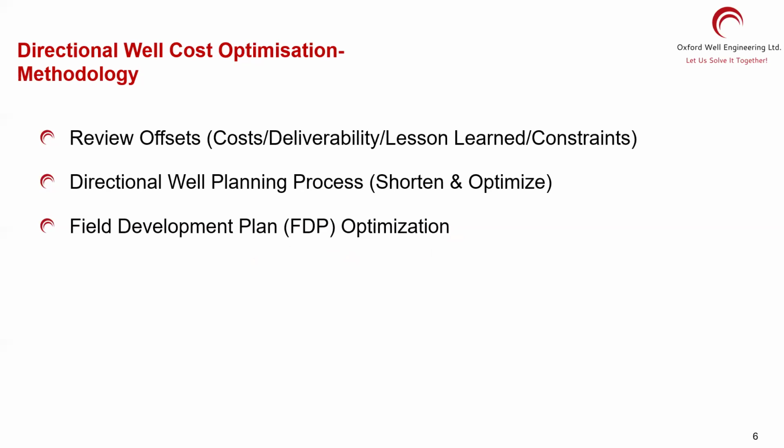Well design selection. Well design is a partner of the trajectory. The trajectory and well design go together. If you have a very nice trajectory and a very bad well design, meaning the tubulars, the way you will be doing the drilling and the technology, the mud system and everything, and BHAs and the pipes, nothing works. You need to work them together. So you need to look at the well design and make sure your trajectory fits nicely, and that they go together without any issues.